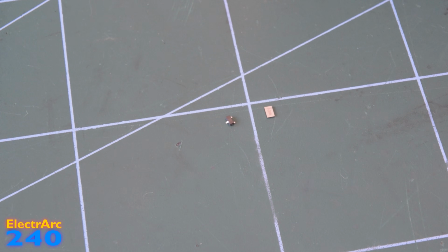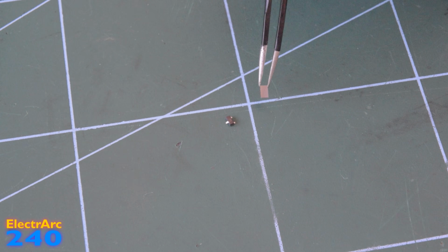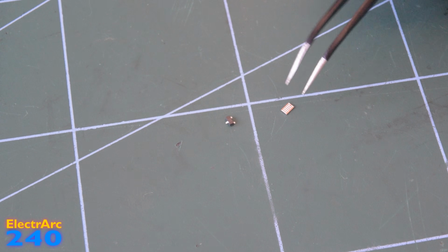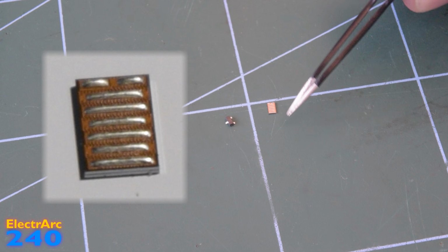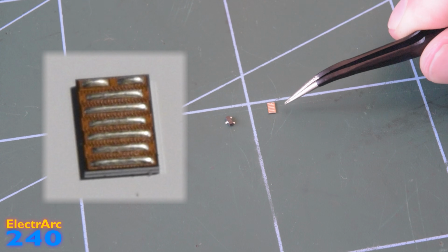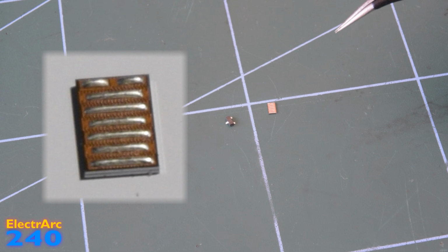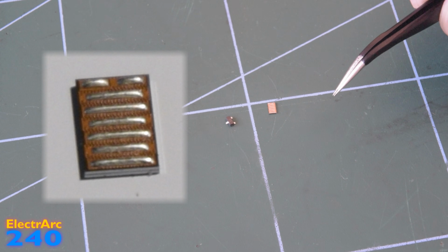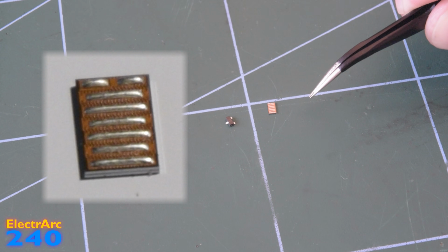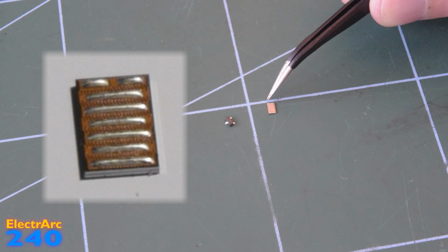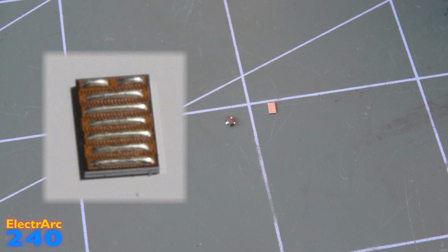Something that's really cool to see on the gallium nitride devices is the way they package them. So you can see, hopefully, with the reflection on the light, this is actually a silicon die. And they've just put some solder on the bottom, a bit like a BGA package. Now, I'll include a picture so you can see the bottom of it better, but those stripes of solder actually interleave drain source, drain source, drain source, and that's to keep the parasitic inductance as low as possible. And that's something that's really cool with the advent of gallium nitride especially, is that packages have had to change dramatically to bring down the parasitics. Otherwise you wouldn't be able to get the benefit that the actual semiconductor can provide. The two little solder pads at the top are the gate and the Kelvin source, which I mentioned earlier.